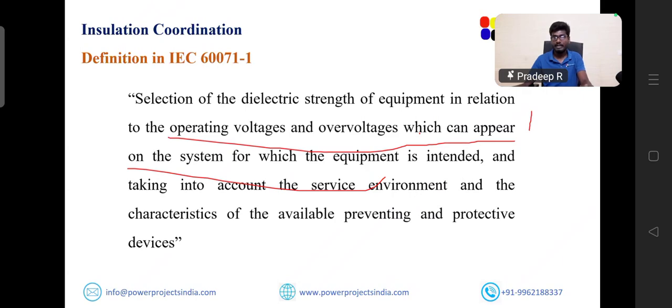If the switching or lightning over voltages, which occur internally or externally, are within the limit, our surge arrestor must withstand those over voltages. And after clearing of that over voltage, our system must once again enter the normal steady state, so that we can select the capable surge arrestor for our system.